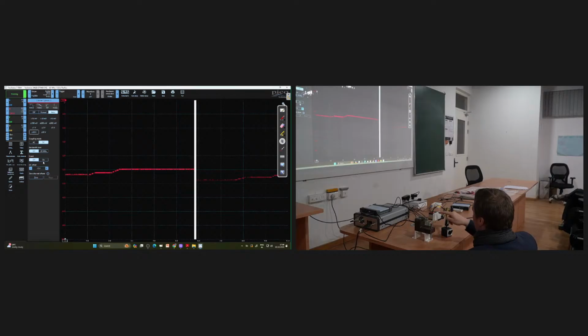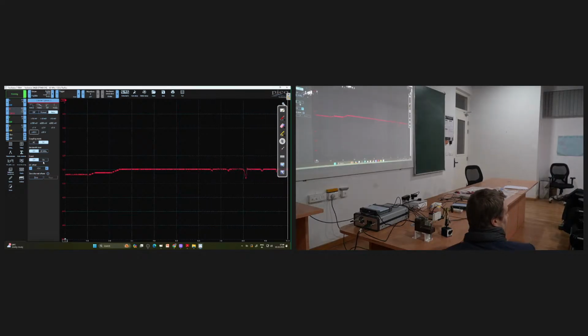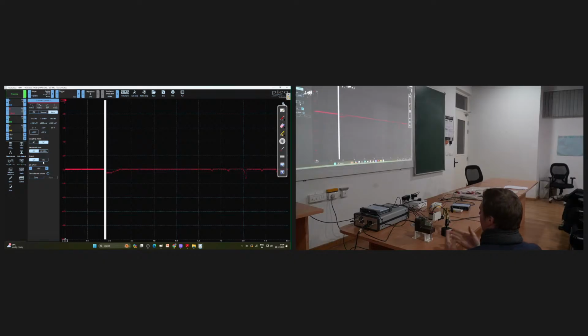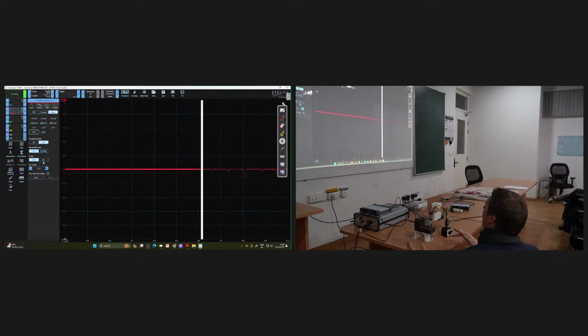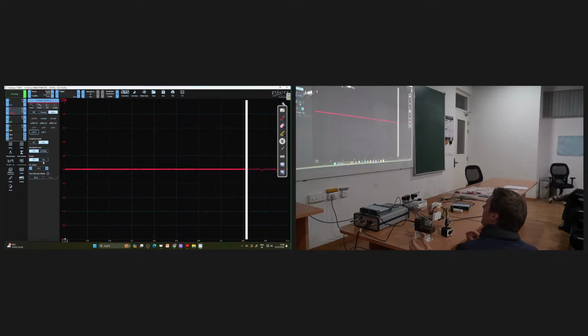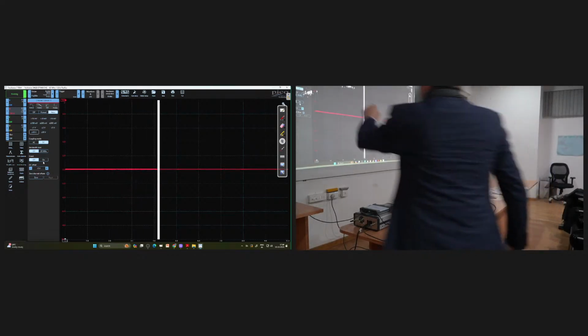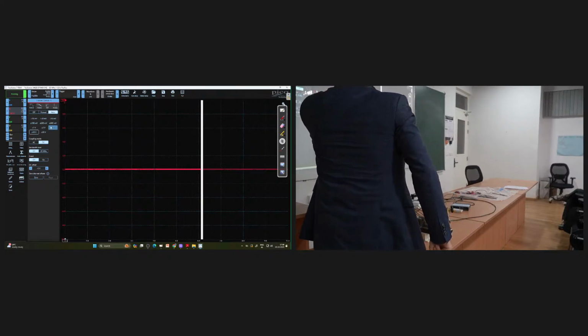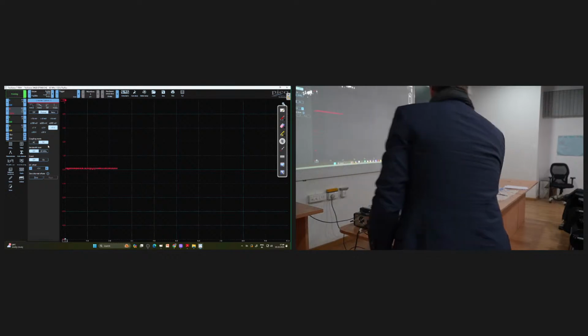And now if I push it a little bit, you can already see that it reacts, right? But that was only me. The rest is purely static. Okay, so that is the first thing. Now we have the signal. Now we can see between negative 10 and 10 volts, and maybe you can switch that in the channel to plus minus 5 volts. Can you see all the numbers written there? Yeah, exactly. Just put on that. Okay, now we see a little bit more. So the signal is getting bigger.